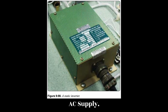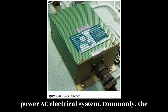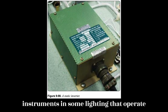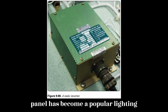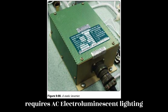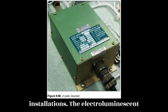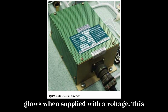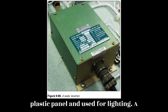AC supply. Many modern light aircraft employ a low-power AC electrical system. Commonly, the AC system is used to power certain instruments and some lighting that operate only using AC. The electroluminescent panel has become a popular lighting system for aircraft instrument panels and requires AC. Electroluminescent lighting is very efficient and lightweight, therefore, excellent for aircraft installations. The electroluminescent material is a paste-like substance that glows when supplied with a voltage. This material is typically molded into a plastic panel and used for lighting.